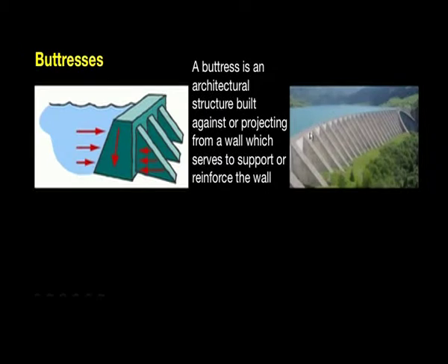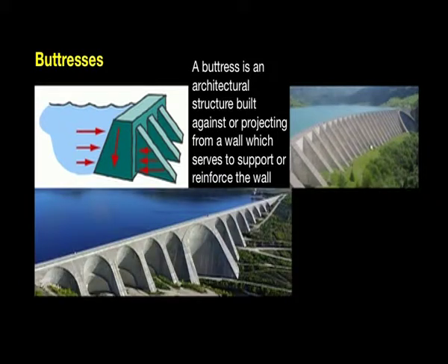If you do not think you have seen buttresses in day-to-day life, think again, look at these pictures. I am very sure you have seen buttresses in day-to-day life. This is a dam. The wall right in the middle needs to take the load of the entire water that it retains. Since the wall cannot do this job alone, we have these helping structures to take the lateral loads. Same is the case with this dam.